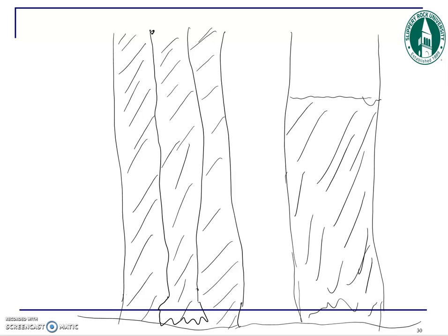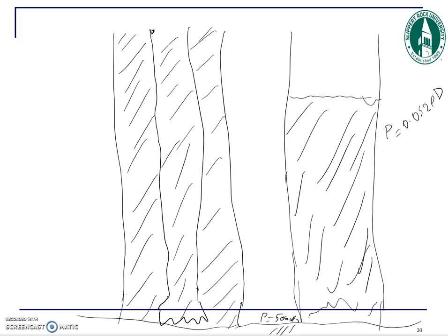So go back to the discussion that we had in the class. Drilling fluid also provides a hydrostatic pressure at the bottom. So let's say there is a formation here where the pressure is, I don't know, 5,000 psi. Now if this level drops, then what happens to the bottom hole pressure? It drops as well. Why? Because the pressure at the bottom hole is calculated by this equation, 0.052 times mud weight times depth. This is pound per gallon, this is feet, this is psi. So since the height of the drilling fluid dropped, the pressure drops as well.